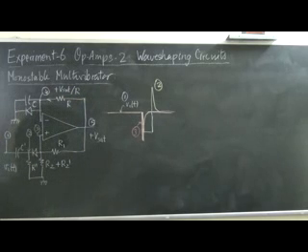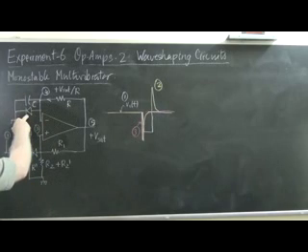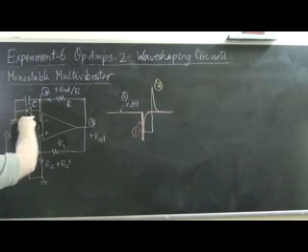So what was the capacitor doing? The capacitor did nothing because it was shorted across by a forward biased diode. So the forward biased diode keeps the capacitor voltage at nearly 0 and hence also allows all the resistor current to pass through itself.